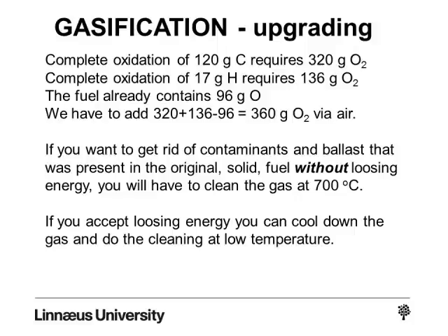You might even revert to, in the most advanced cases, a pressurized gasification process using pure oxygen and water vapor as the gasification media. Doing that, the gas quality, the product gas quality, may even be synthesis gas, which is mainly composed of carbon monoxide and hydrogen with only very small amounts of methane in it.